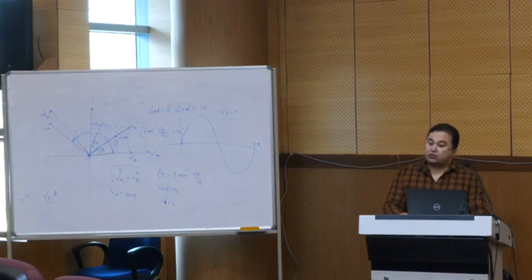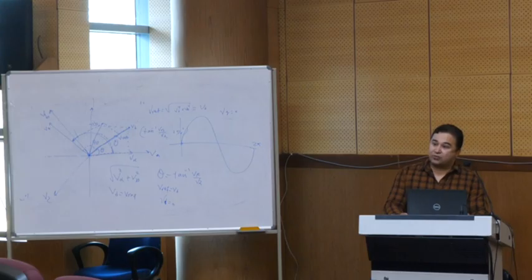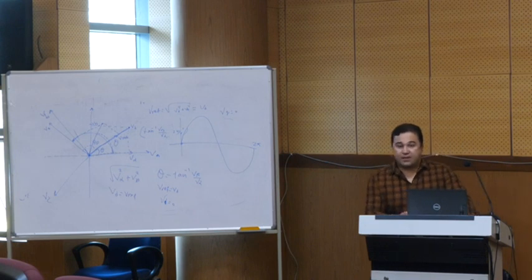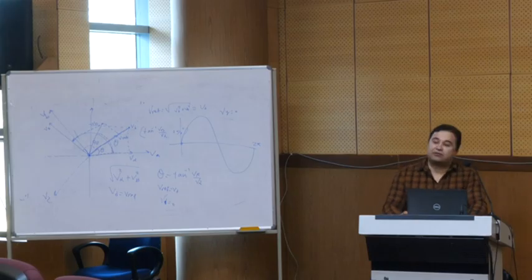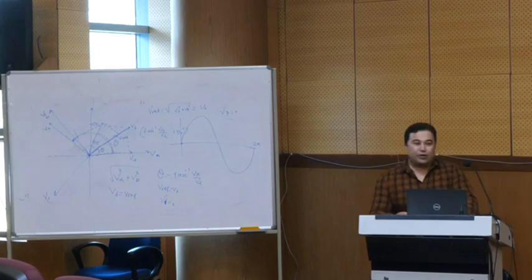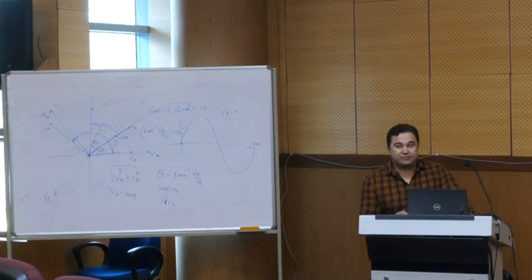But when you go to the grid connected mode, it is much better to consider Park, because you can separate the fundamental frequency from the harmonic frequency, and then compensation will be much easier. Later we see that decoupling is not that complicated, at least in the paper.